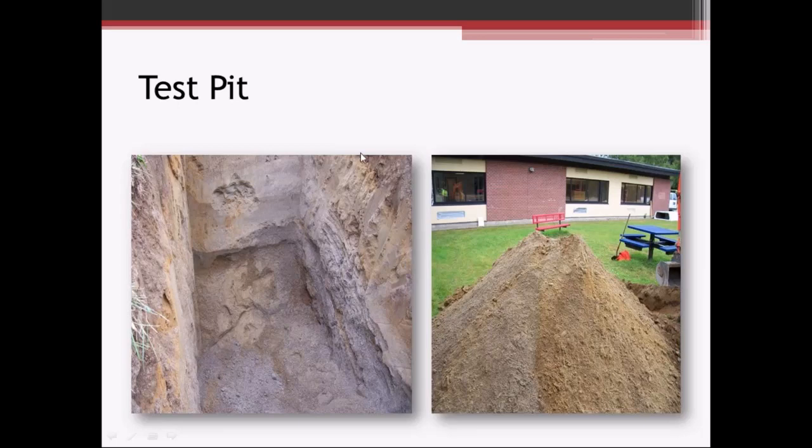But based on the test pit photos here, you can see there's soil layering. You can see the different layers of soil. So it looks like there's some finer grained soils up here, and it gets into a coarser sand as you go with depth. So the engineers are going to determine where to collect the samples, whether or not to take a discrete location or a composite sample. So for instance, if the geotechnical interest is a foundation 4 to 5 feet below grade, the engineer would probably want to grab a sample within this layer.